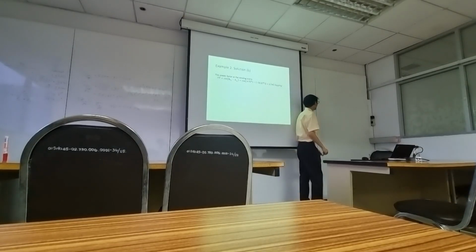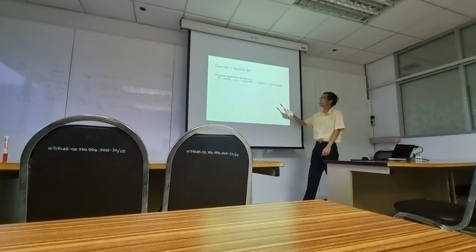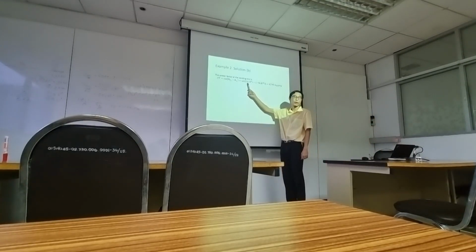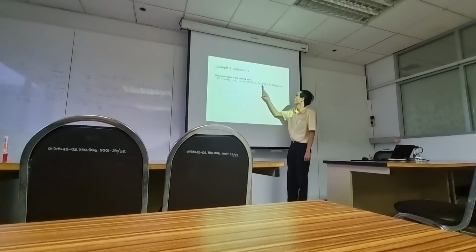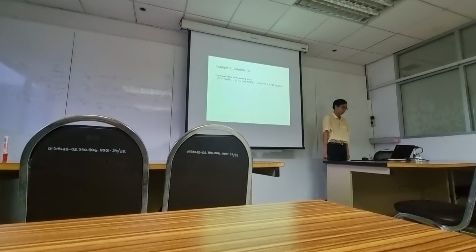If you want to calculate the power factor at the load, you can see that the angle of the voltage at the load is zero, so sometimes we just take only the angle of the current in the calculation. But for VS, the angle of VS is not zero, so we also have to include this. The power factor at the sending end is cos of theta v minus theta I, and you get 0.7 lagging power factor.